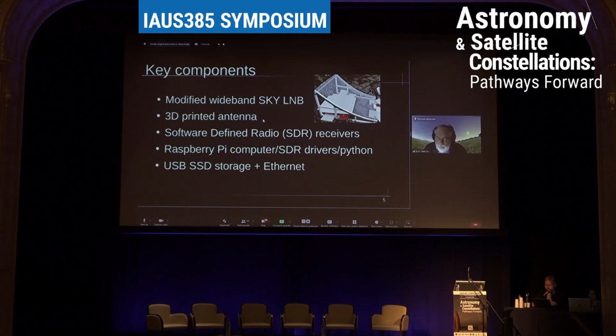And you can actually just use a Raspberry Pi computer to log the data, and that can just run 24 hours a day. And you can use Python to do some of the online processing, produce plots every 10 minutes, and store all that to a relatively cheap SSD, which you can plug in and get data transferred over the internet.